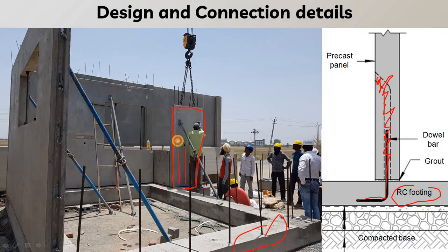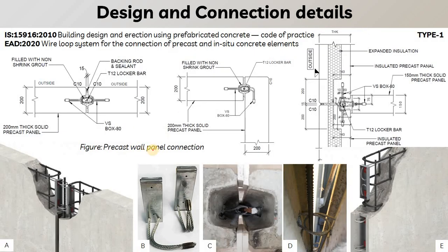Now the panel will be passed through this reinforcement, and then this hole will be grouted with this special cementitious grout, which is high strength grout.